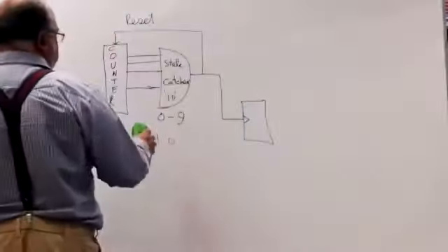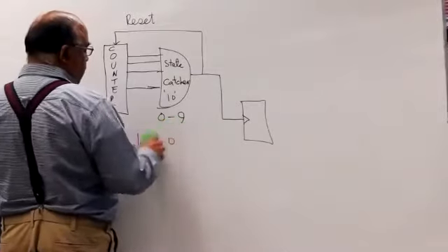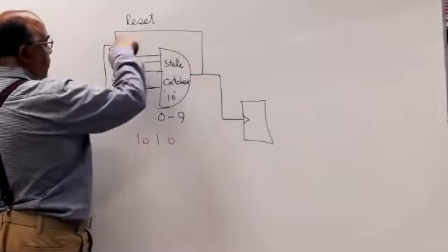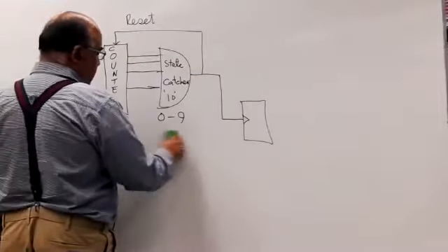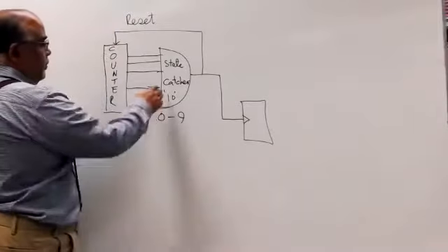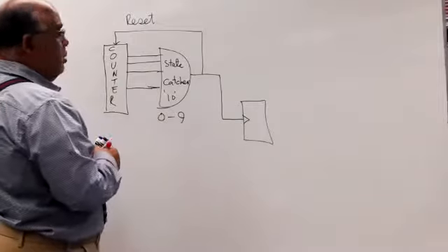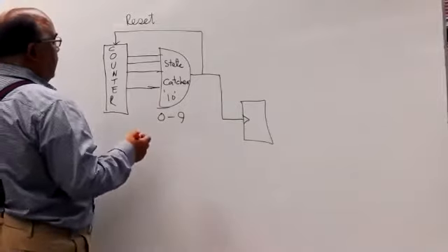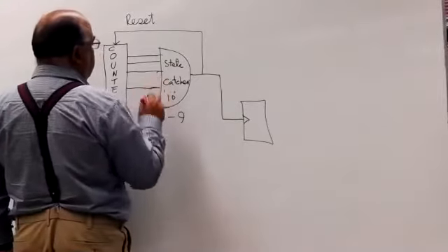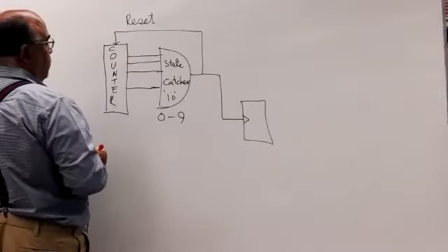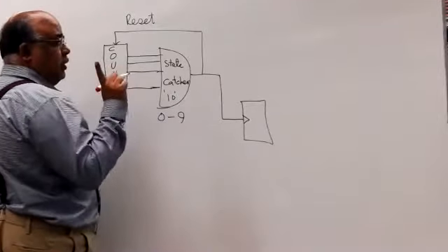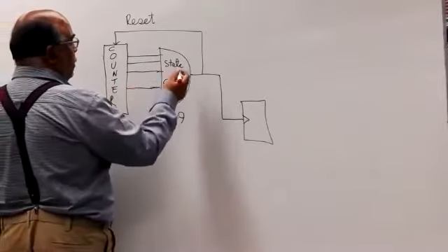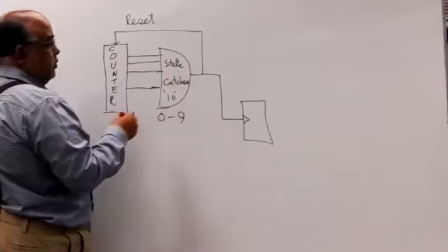So basically if you want to make a state catcher for a counter for 0 to 9, you catch state 10, so that when 10 appears in this, the output becomes 1 and it resets the counter. So this is that state catcher. So the problem lies here that I found out, a problem that a lot of you may face, that I also faced. So it's not just for this; when you are going to do some project like a clock or alarm, you may also face this problem.